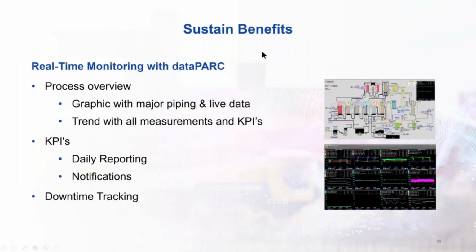So how do we do the sustainability? We do real-time monitoring with DataPark in a couple ways. One of them is you make a process flow graphic that has everything on that processing unit on it. You don't have 4 or 5 screens where you're bouncing between screens trying to see what's going on. If you're troubleshooting or trying to teach somebody, you need a one-stop shop where you go look at it. So part of what we do is make sure we have these unit operation screens built for troubleshooting.